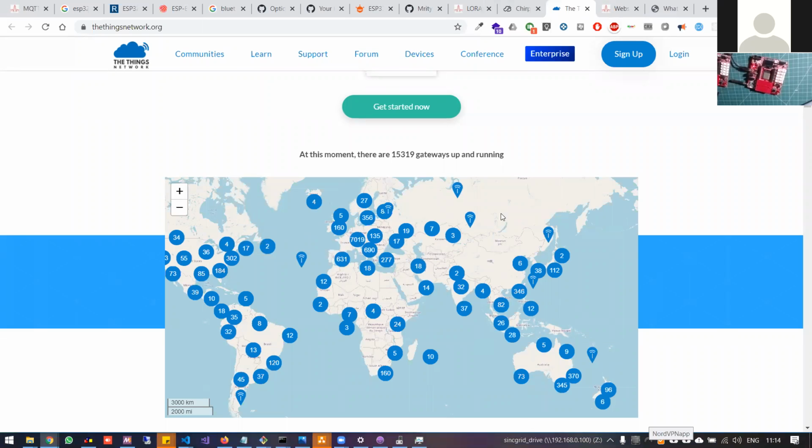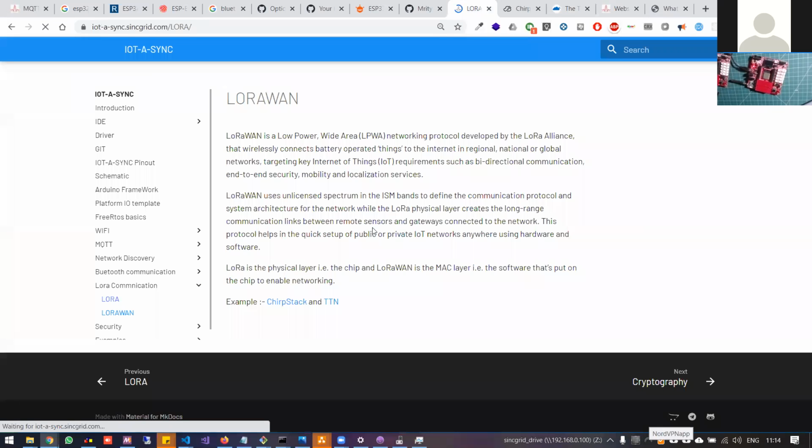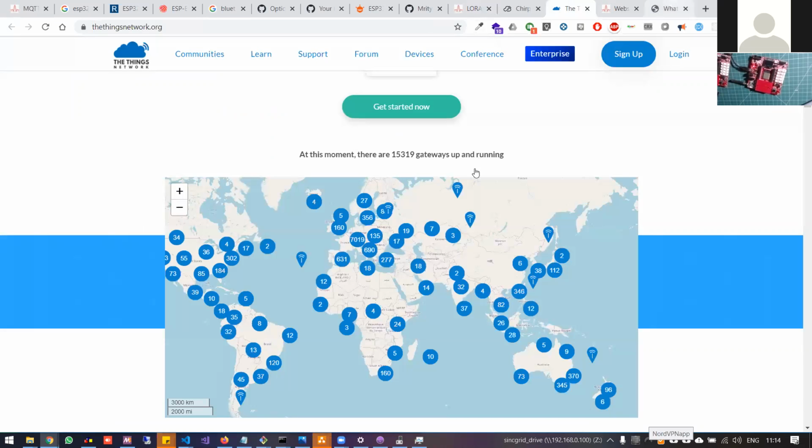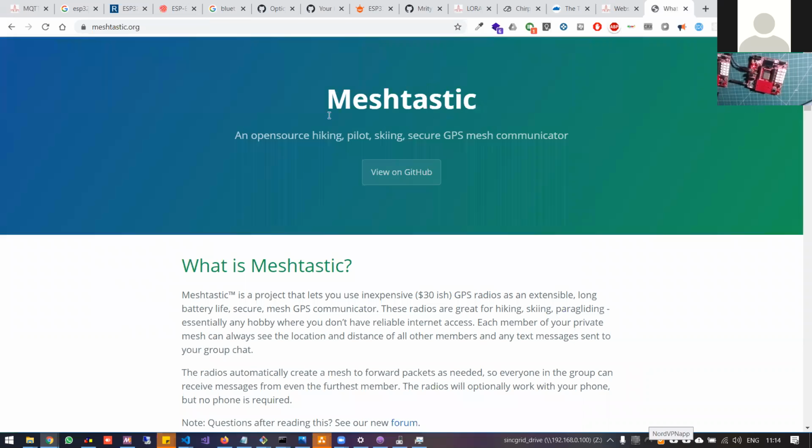There is also the physical layer, as well as a LoRaWAN code available, but that WAN code needs the central gateway for its deployment, and you can use that gateway in the star topology. So LoRaWAN supports star topology. You can use Meshtastic, which doesn't need any gateway. Everything can just start to go. This supports the mesh network, and you can just go with it.